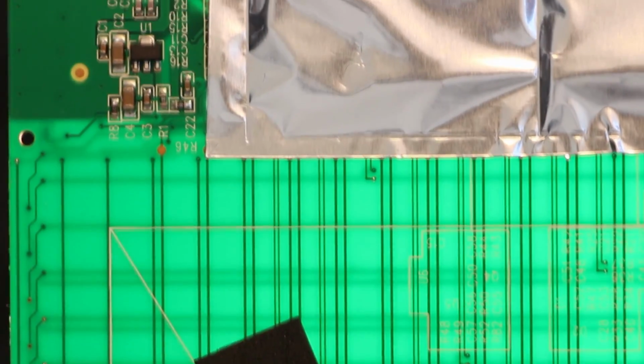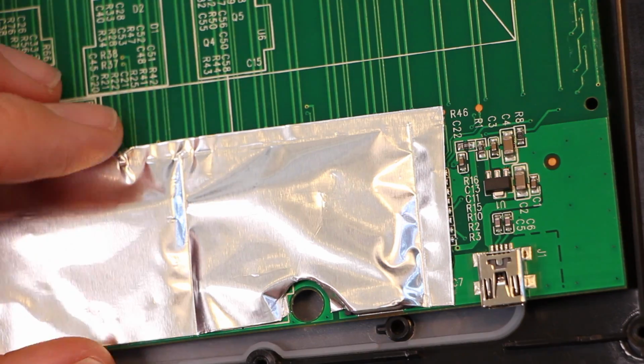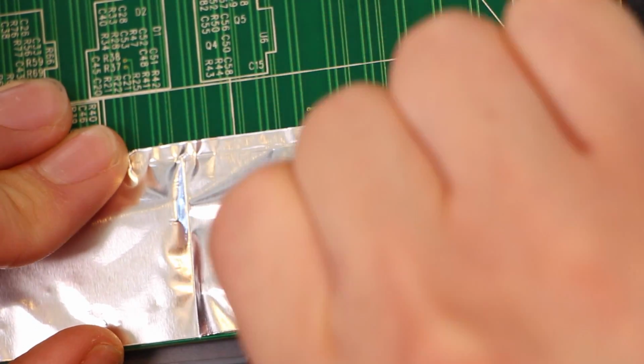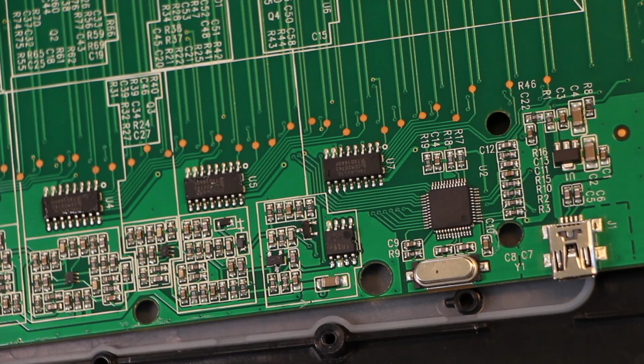These coils can each enclose plenty of area, but they only have room for a single turn of wire, so they can't convert the magnetic field into very much electricity. This receiver circuit will need to be very sensitive to the electrical signals coming out of this matrix of coils. So all the shielding helps protect this receiver from any external electrical signals.